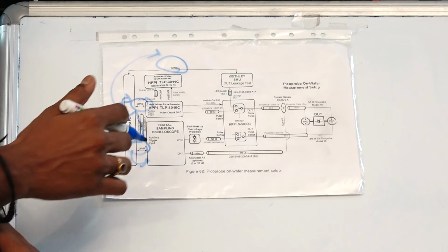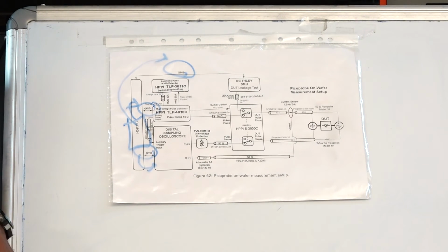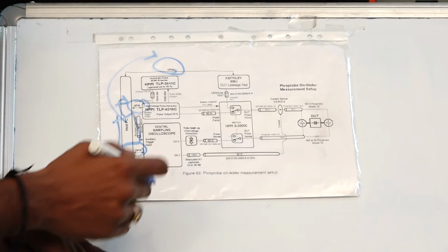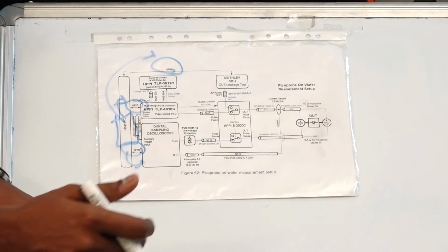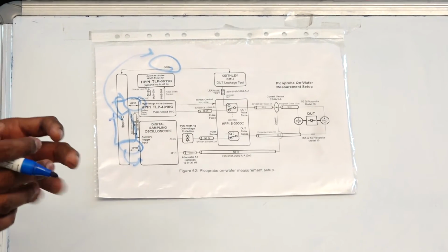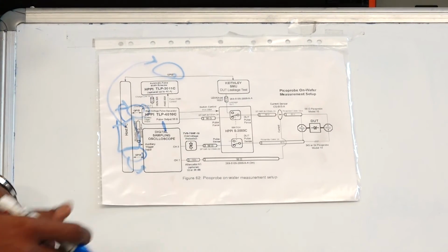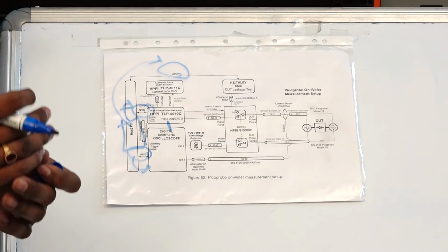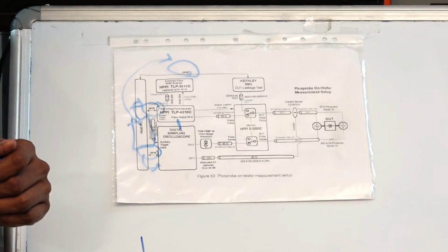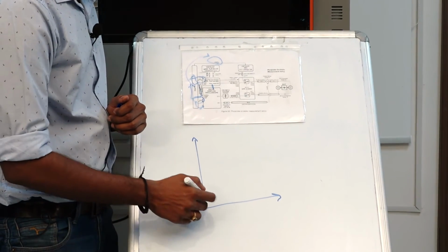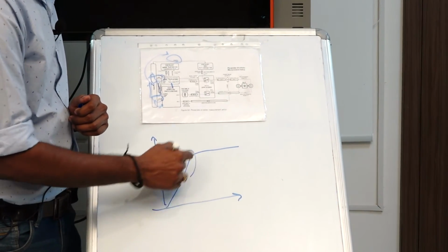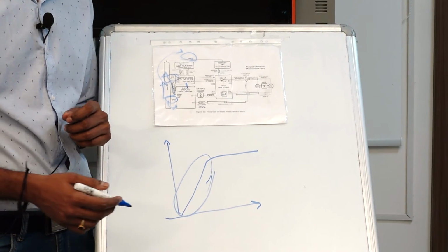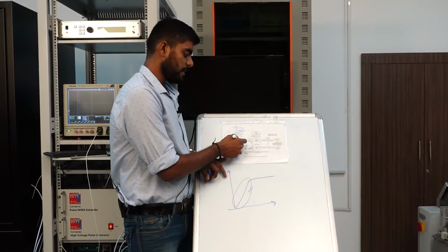Now between the oscilloscope and the pulse generator there is also a trigger line. This trigger line is important because the TLP generator also has to tell the oscilloscope that it's time for you to do the measurement. The trigger line between these two carries a voltage signal. In our case, we have set the oscilloscope so that whenever it measures a rising edge of the trigger signal, say if this is the signal, that's when the oscilloscope gets triggered and gets ready to do the measurements. So this is how the TLP generator and the oscilloscope talk to each other.